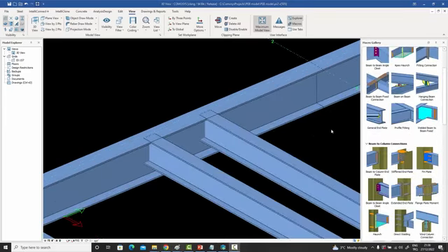Now let's talk about the welded beam to beam fixed connection. This is very convenient when you have a beam to beam fixed connection. Normally for floor beams, we have simple connections, but occasionally with cantilevers or things like that, we have fixed connections. And there are different ways to do that. We can either have a bolted one, but then typically the problem is that the size of the main and the size of the secondary is not the same.